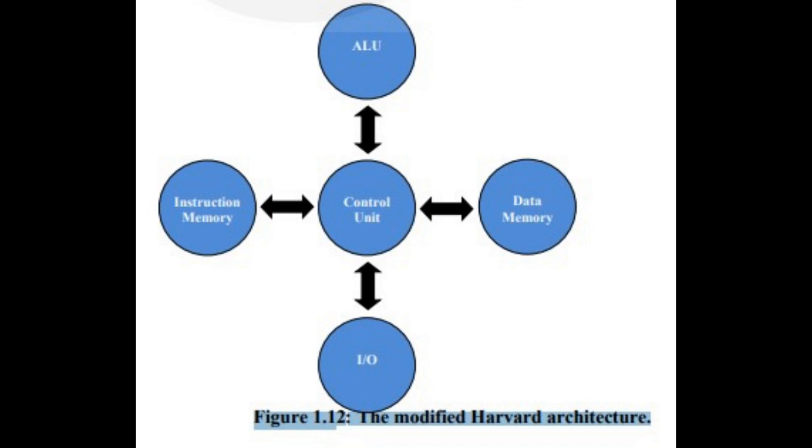An ISA includes different kinds of instructions and sizes of different instruction formats. These concepts will be explained in more detail in Block 3. The following example of MIPS ISA very briefly defines the description that should be supported by an ISA. You may refer to further readings for more details on this ISA. 1. ISA defines the types of commands that the processor will support. Depending on the class of work they are doing, MIPS instructions are divided into three types: arithmetic and logic instructions, data transfer instructions, branch and jump instructions.